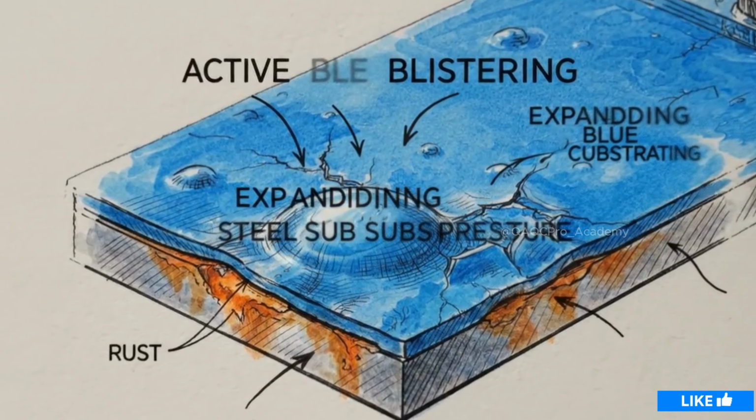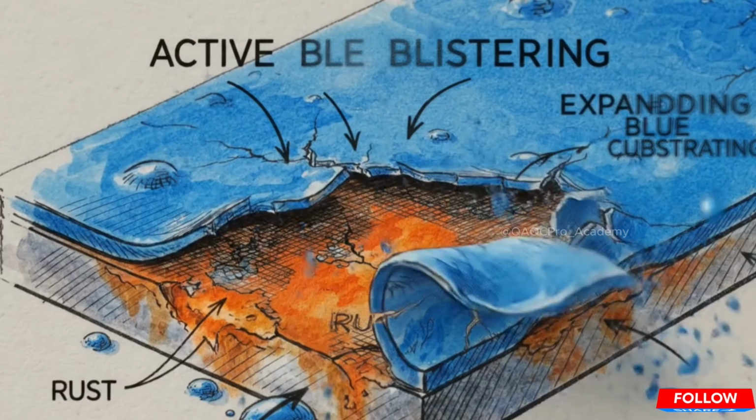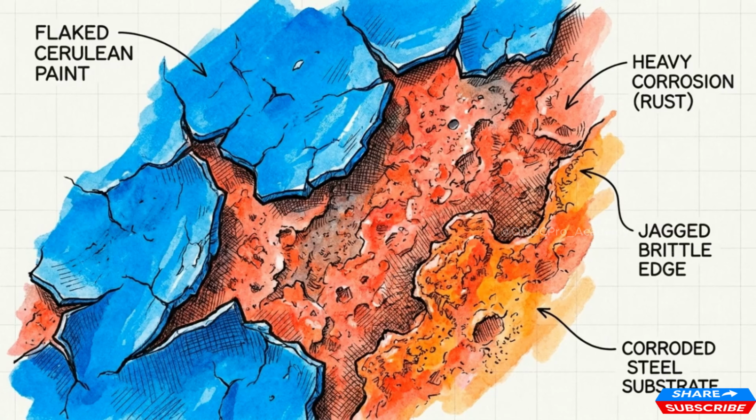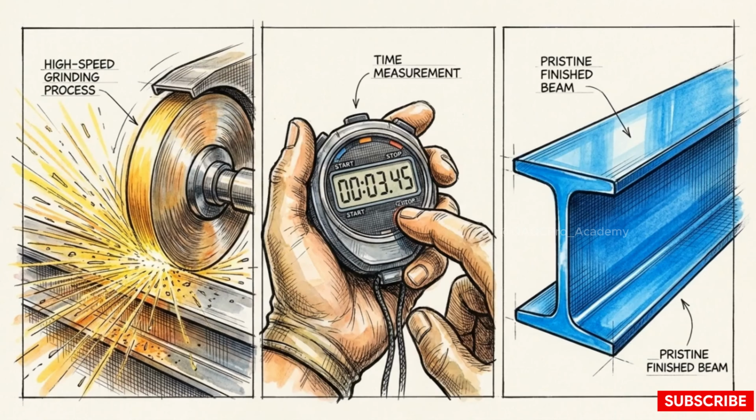When surface preparation fails beneath a heavy industrial coating, the result is immediate and expensive. The paint blisters, tears away from the steel, and leaves the bare metal completely exposed to corrosion. Preventing that failure comes down to one primary decision: the abrasive media you load into the blast pod. That single variable dictates your cutting speed, your labor costs, and the ultimate lifespan of the coating.